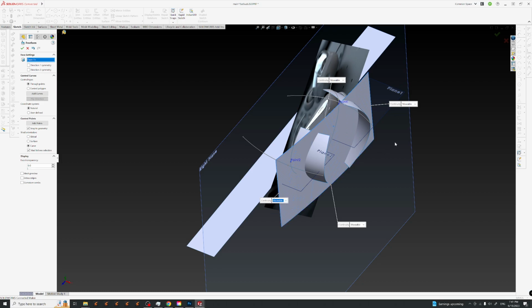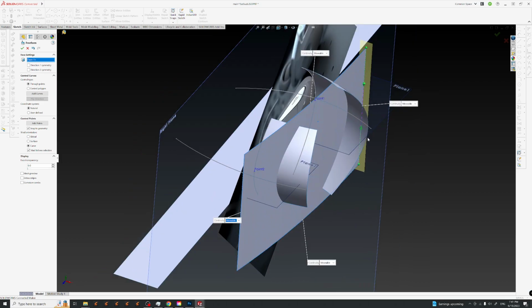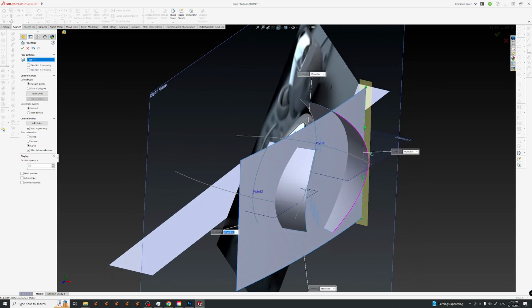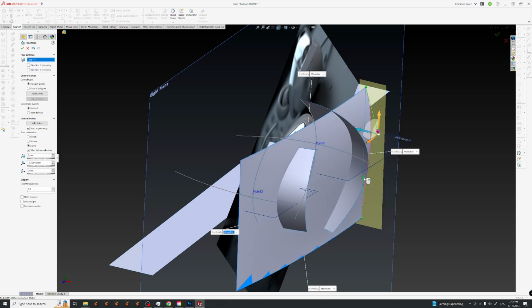All right, and after we put them in movable, we have something really powerful in here. These arrows here are the tangent handles of the surface. So that means that if I am going to modify the tangents, another thing, I do not want snap to geometry. I know the control points, yes, I do want them.